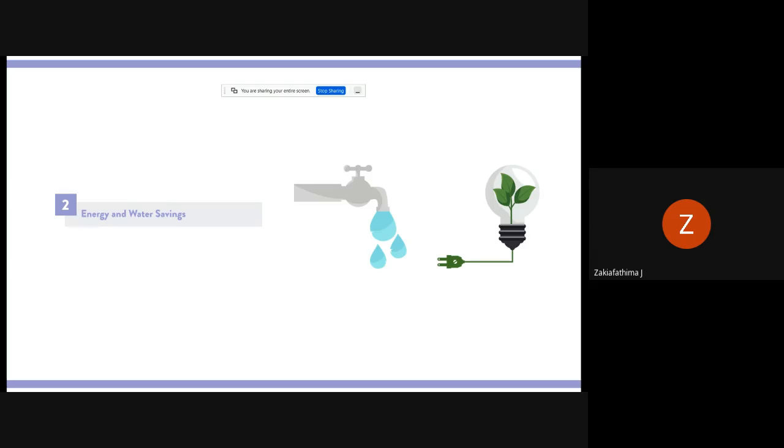Once you look into your LEED for ways to save water use, there are a lot of rules given. For example, your shower area needs to have a flow rate of 9.5 liters per minute, and your toilet flushes should be only some 6 liters per flush. Then public faucets should be 1.9 liters per minute. So you have these kind of rules that you need to follow.